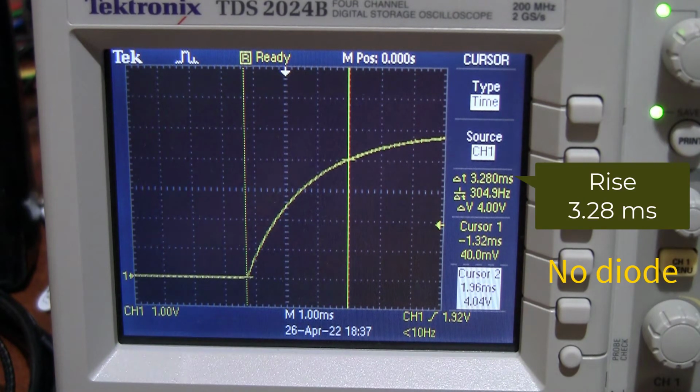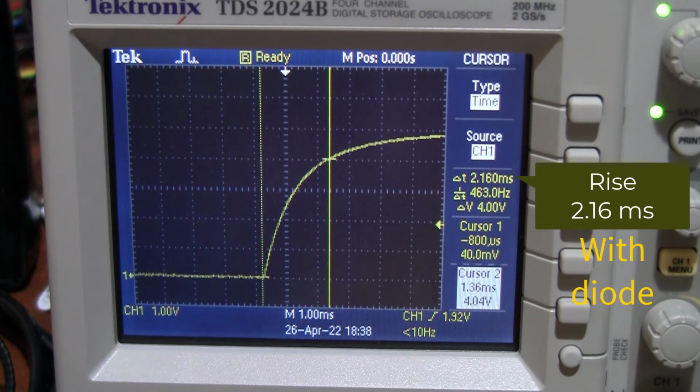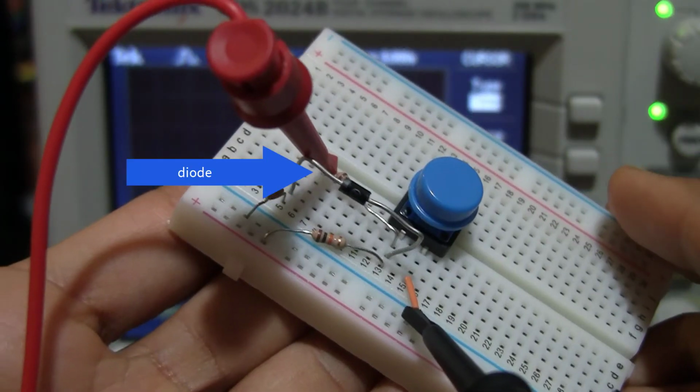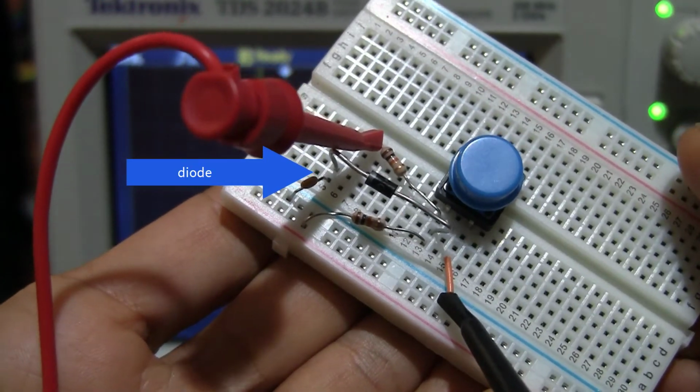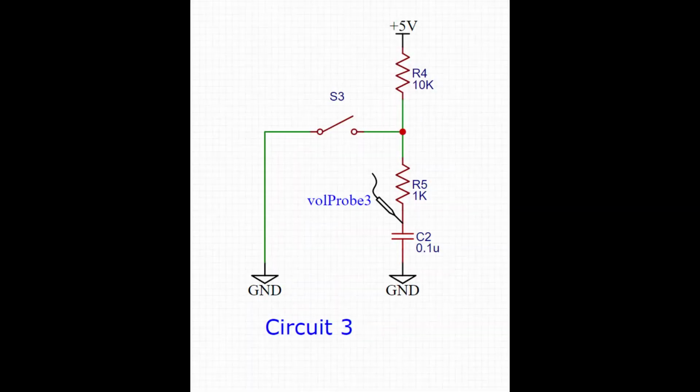And I will show what the diode looks like in a later picture. It's just a cheap old 1N4148, nothing special. Ideally one wants to use a Schottky diode for that location because it'll have a shorter rise time and also a smaller voltage drop across the diode.